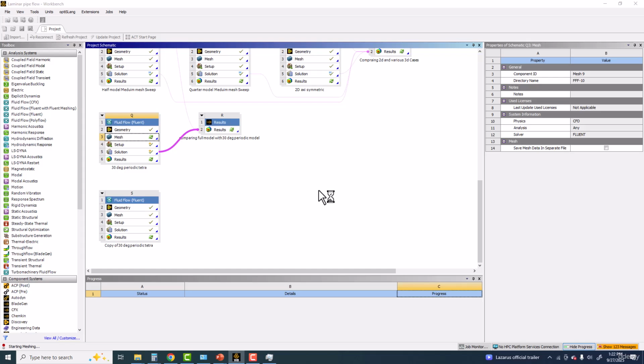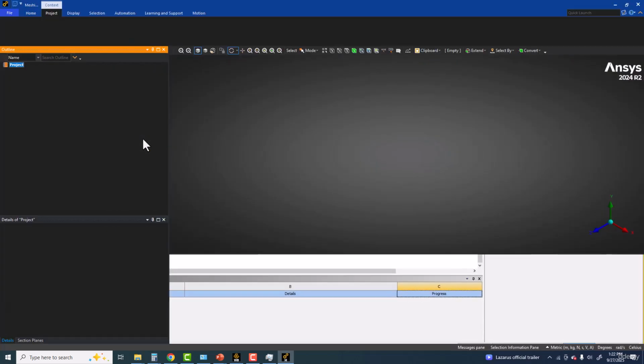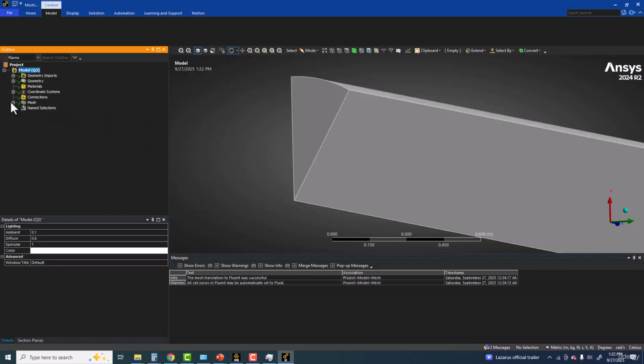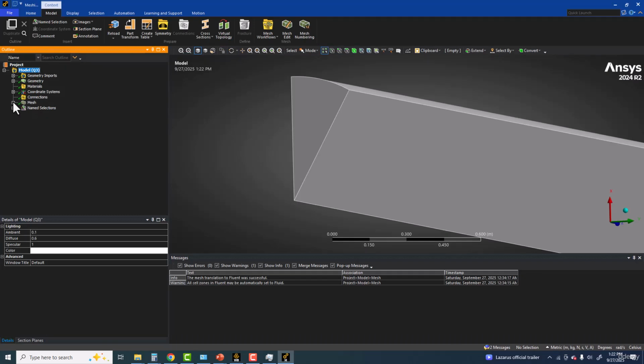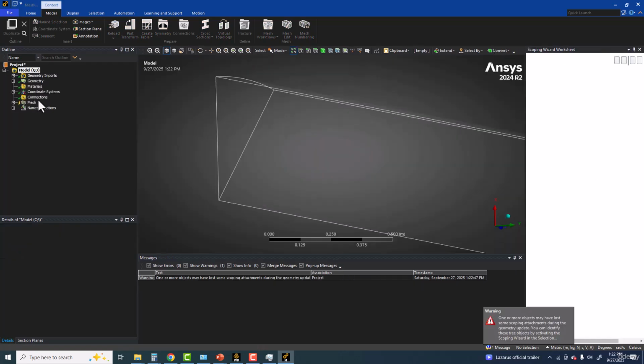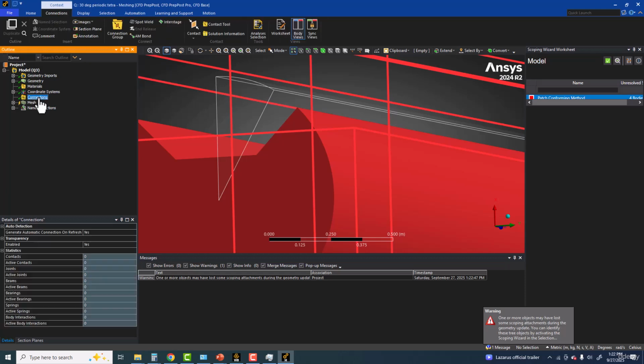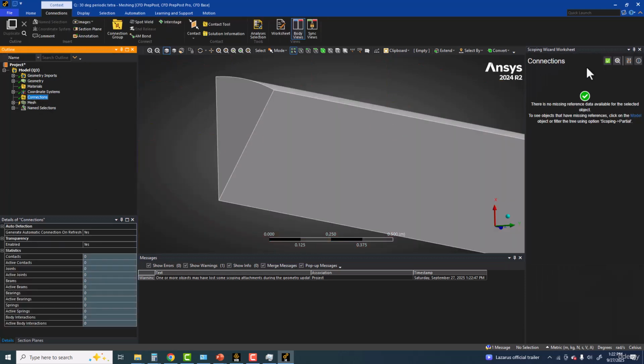It's a tetra meshing. I define the sizes on the periodic surfaces and also on the inlet and outlet. The top wall is going to get the meshing from the size function. Let me show you. One more thing is that there should be no connections here, no interfaces should be there. So delete the contacts directly: instead of deleting each contact, go to the contacts in the connection and delete them directly from there.